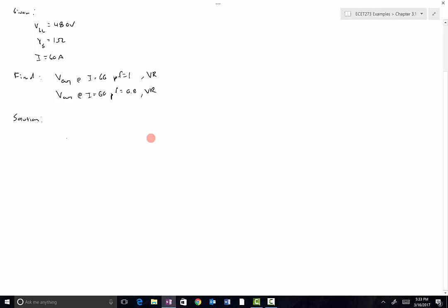So we found that the generator had been set such that EF is equal to 277 volts. And again, EF is the excitation voltage of this generator. We've got a real simple generator. There's just a synchronous reactance and an EF. And then the output voltage on a per phase basis is called the terminal voltage. So we've got EF here is 277. That just came from dividing V line to line no load by √3. So that's 480 over √3.